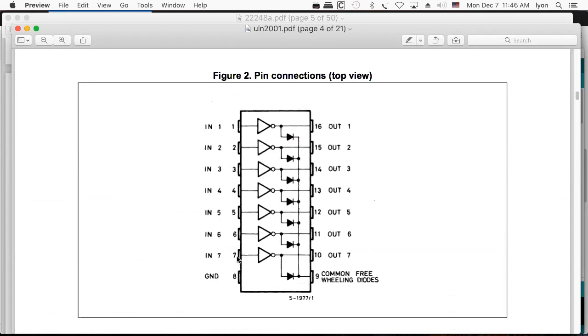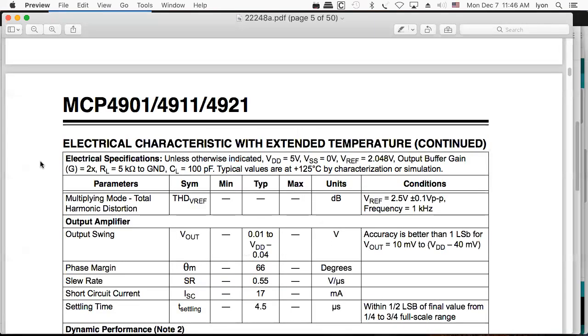If you put an input in that's a 0, the output will come out as a 1 and vice versa. So that's a nice way to go. If you want to increase power to 2 amperes, I guess you could stack 4 of these things, but at some level you want to call it quits and just buy a different chip.